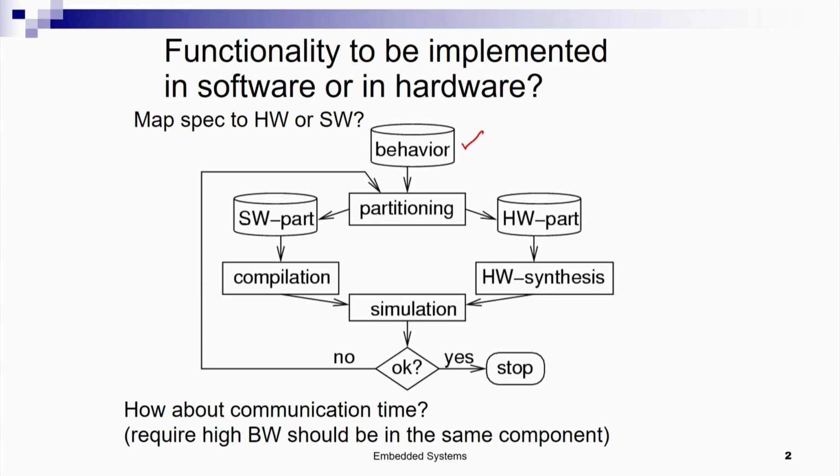You do not have to bring in machine instructions as in a general purpose processor. You just take the data, and the data is transformed through a set of digital circuits and the output is obtained. So, the execution time might be much more optimized with respect to a software implementation. The performance of a hardware implementation could be much higher than a software based implementation.